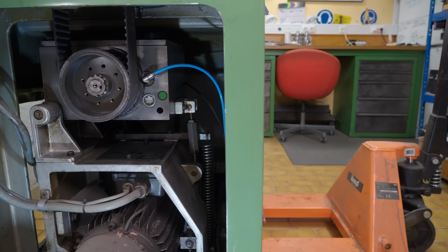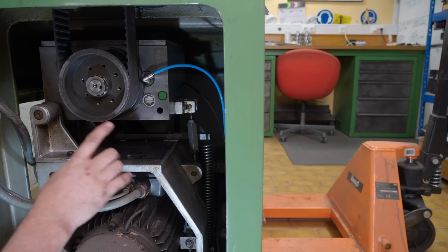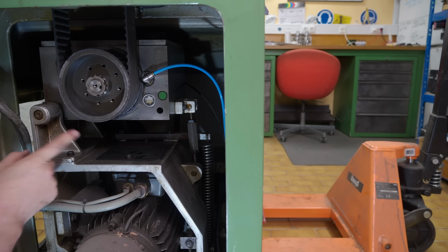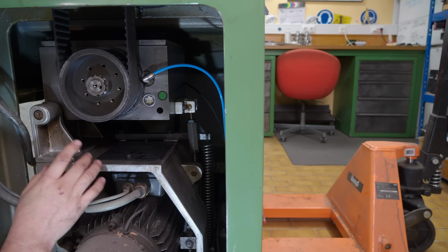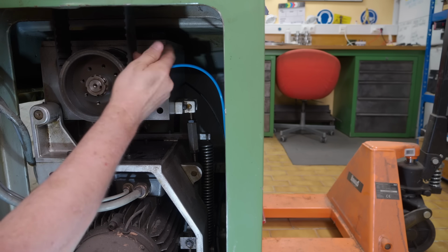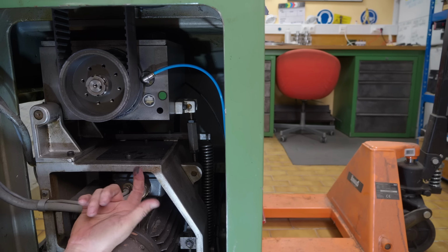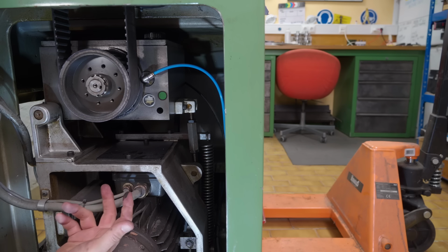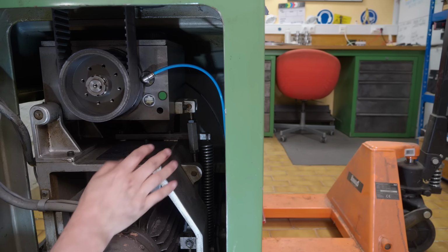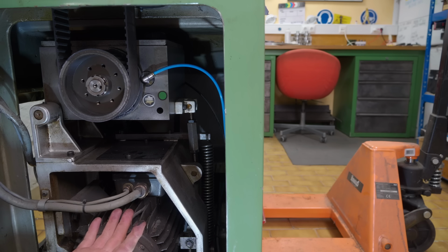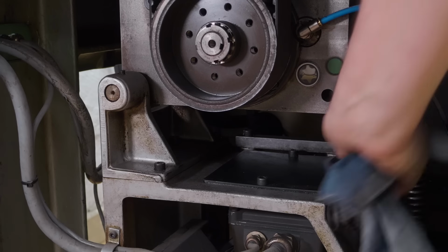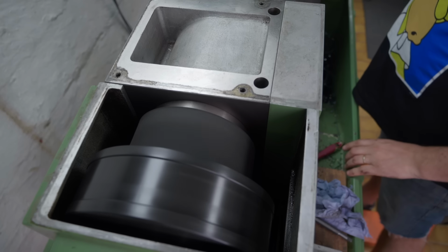There were some comments on putting some form of optical encoder, like on the output of the gearbox or on the continuously variable transmission. But really, this is a pretty dirty area. You've got a lot of belt rubber coming off. It's all a bit oily because of the lubricated air that moves the gearbox. So I really don't think it's a great environment to try using an optical sensor. While I'm in here, I can do a quick oil check. It's looking fine. Let's just run that spindle and see if it's going to ride up.